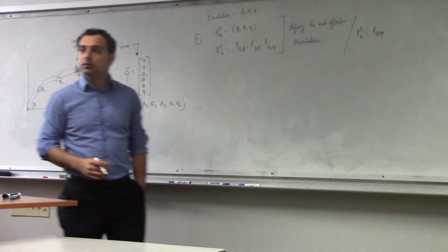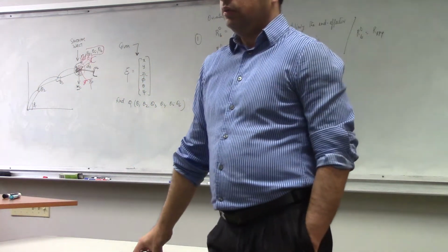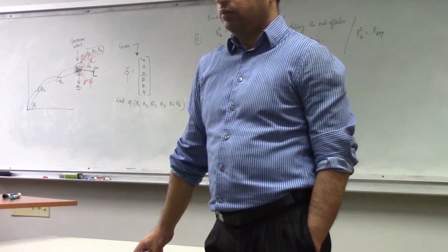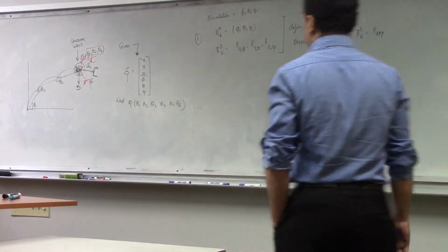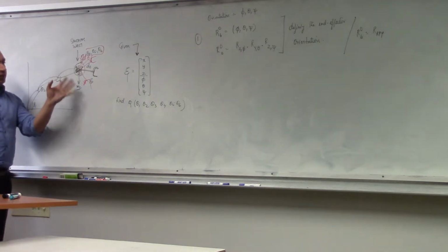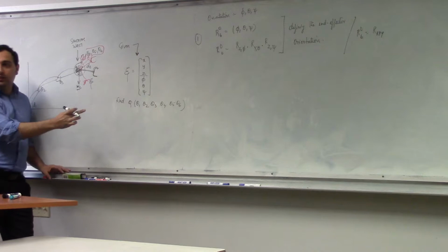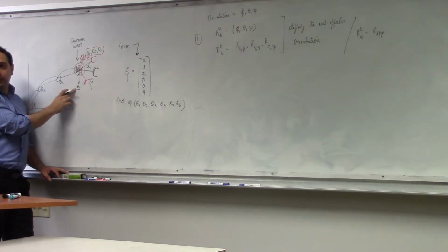Professor, do theta 4, theta 5 and theta 6 affect only the orientation, or the position and orientation of the end effector? We will assume here that given px, py, pz, if I change θ4, θ5, θ6, the wrist center will not change.